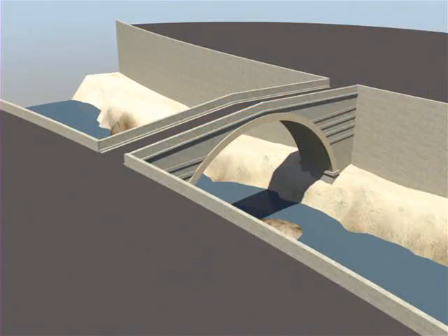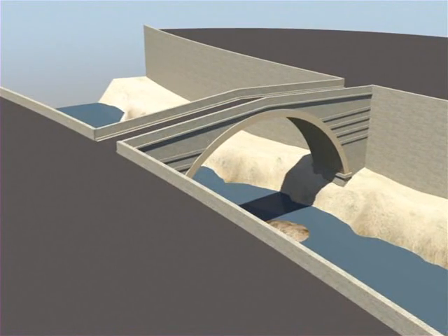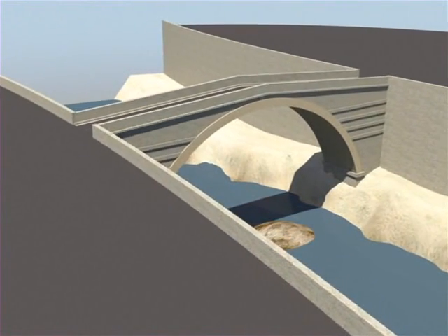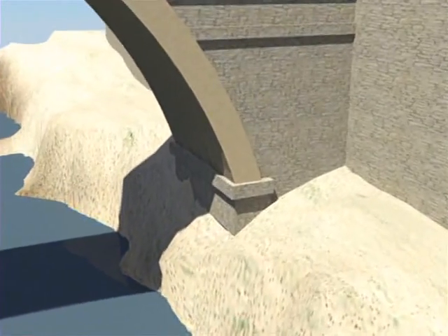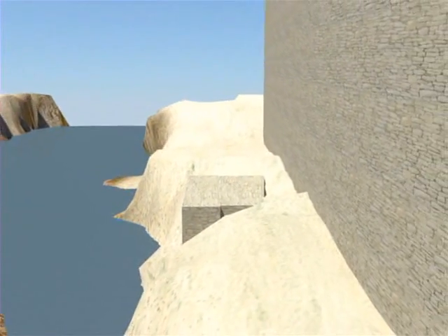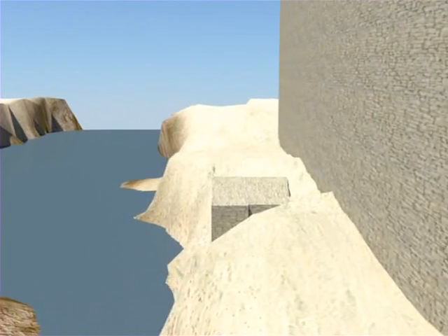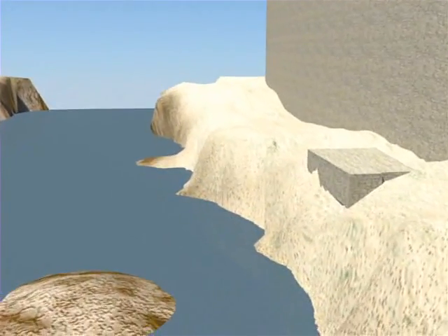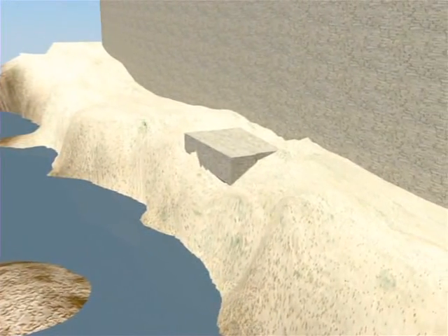So let's examine the structural system of the Pont Saint-Martin. We'll begin by constructing the bridge virtually using this 3D computer model as a way of identifying the main structural elements in this bridge. First, these foundations are cut into the rocky slopes of the riverbanks and then reinforced with stone masonry. The foundations provide both vertical support to hold the bridge up and lateral support to resist the thrust. Note that a steep river valley is actually particularly conducive to this type of support because the steep bank provides something for the arches to react against.